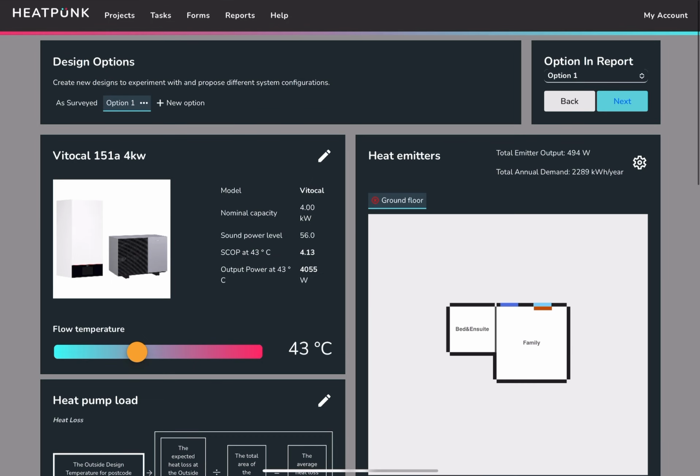So we'll also need to figure out your current electrical load on a survey. So we will use a piece of equipment to measure how many amps your household draws, and we need to mimic the worst possible day for electrical use. And it's often Christmas Day or sometimes around then, where the oven is on, the hob is on, a microwave may be on, a kettle, music, your heating system's on full blast, somebody may be in the shower, where the electrical demand on the property is absolute highest.